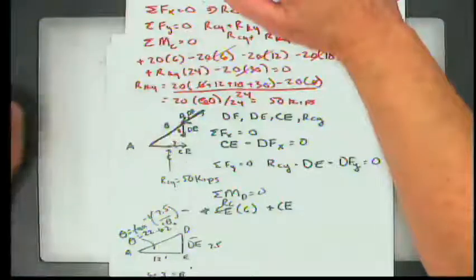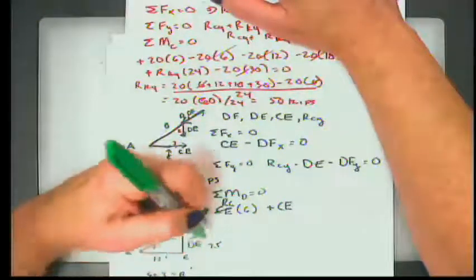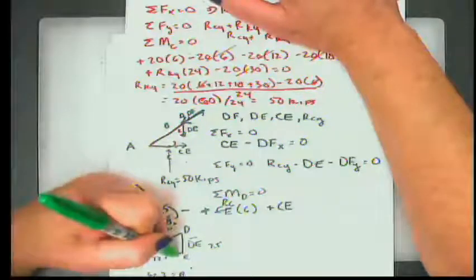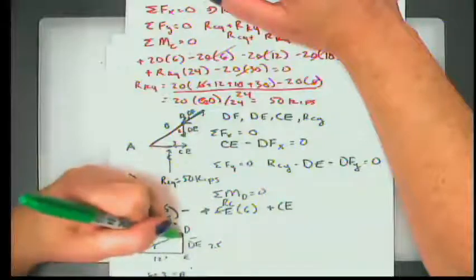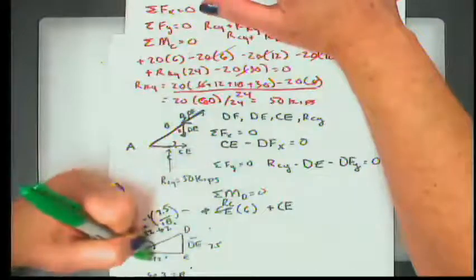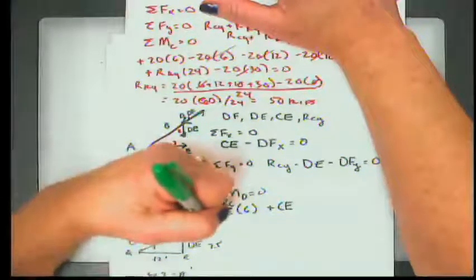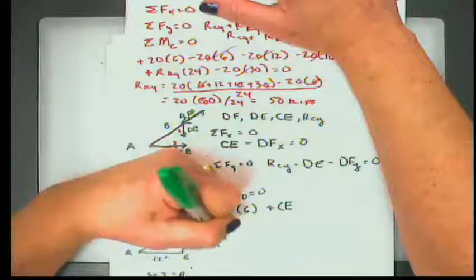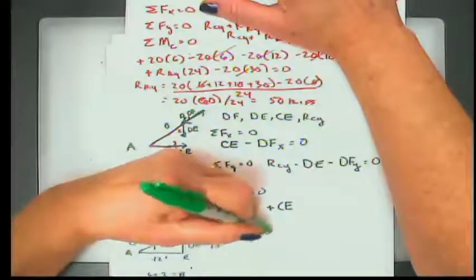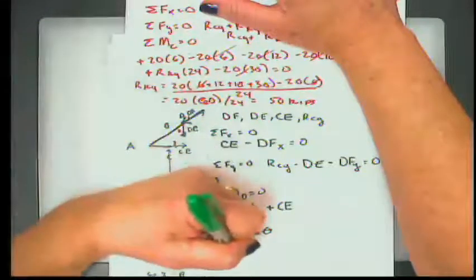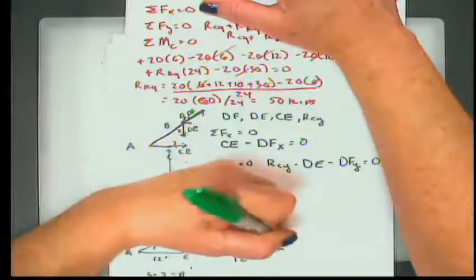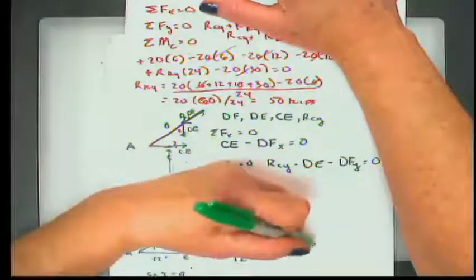All right, so if we have that angle of 22.62 degrees, it's going to be the same when I'm finding this vertical distance. I know that the horizontal distance is 12, and I need this midsection vertical distance. I know the angle, I have the adjacent and I'm looking for the opposite. So opposite over adjacent is the tangent of theta. The opposite is the length of DE, which I'm looking for, divided by the 12 feet, which is the adjacent, and the angle is 22.62 degrees.